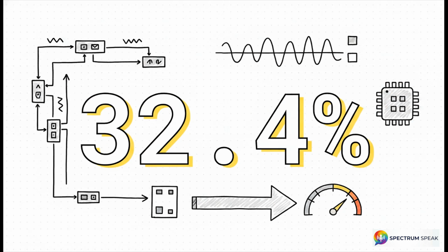The result is 0.324. Move the decimal 2 places over, and we have mathematically proven a maximum bus load of 32.4%. This perfectly and elegantly demonstrates the unbreakable relationship between your frame size, your transmission frequency, and your hardware's bit rate. You now possess the mathematical intuition to prove exactly how much bandwidth is being consumed.